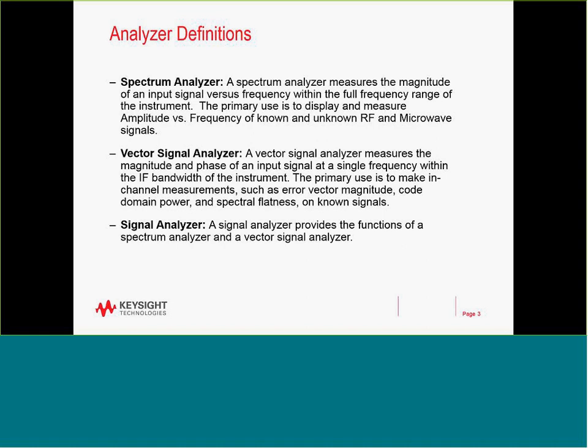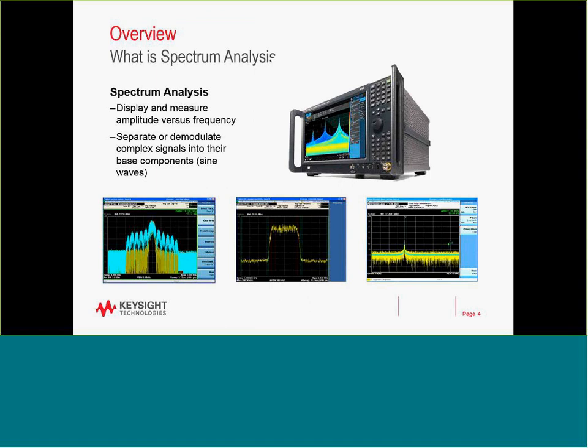I have a tendency to interchange spectrum and signal analyzer, but in the course of this presentation, we're talking about the equipment that has the ability to do both measurements. Signal analysis is really the ability to show the signal, like what we see on the bottom left corner of the display, which is actually a pulse signal that is measured. You can see the sine over x kind of waveform, which is showing this way because it's in the logarithmic display.